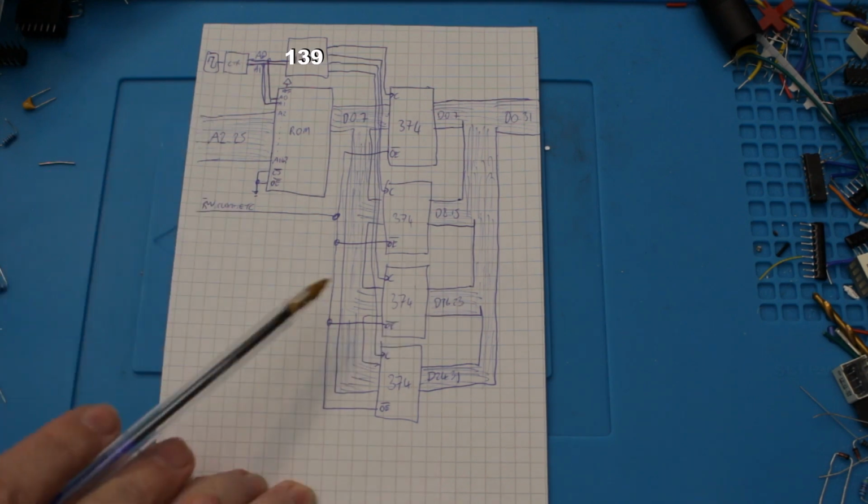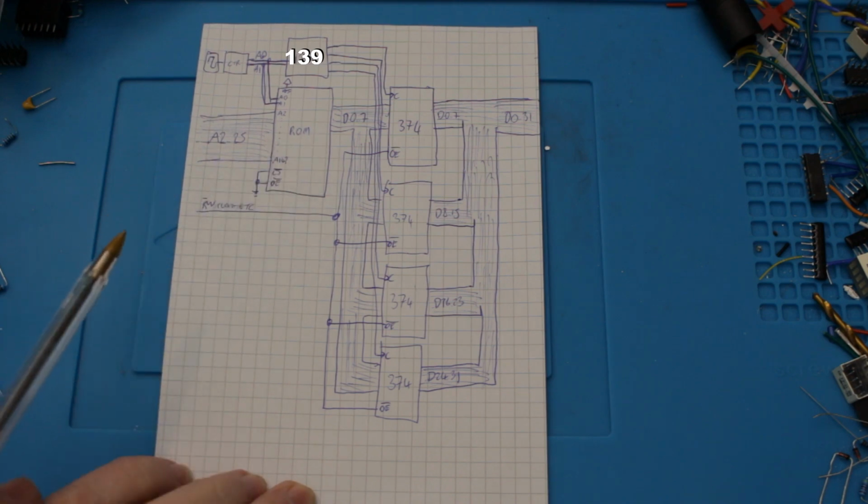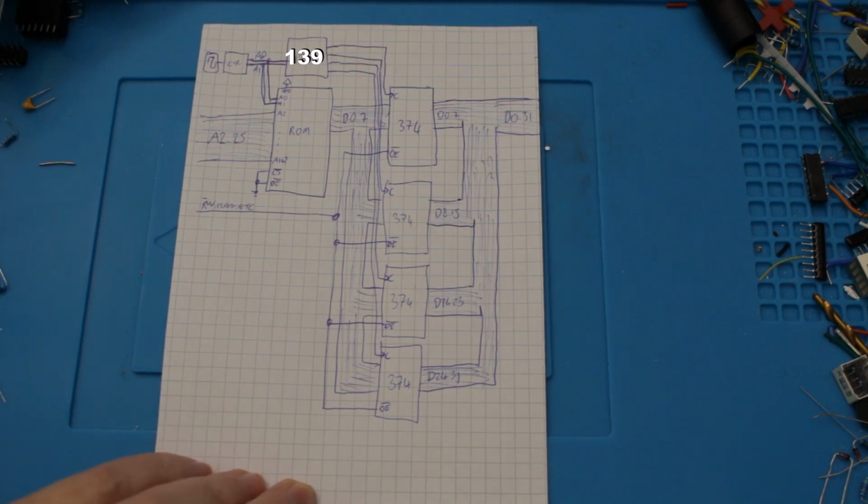Anyway, it's an interesting system, and it would allow me to only have one ROM and program it much more simply than with the first system I showed. This is actually simplified by the fact that ROM is read-only. We don't need to worry about the byte versus word modes on the CPU, because when you're reading bytes, the CPU is quite happy for you to just send a whole word anyway. It picks the right bit out of it, and we're never going to be writing bytes to the ROM, so it doesn't really need to know what's going on with the byte versus word line.